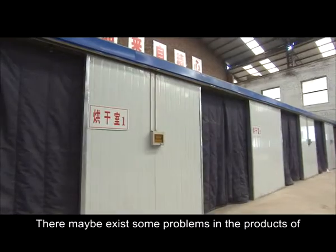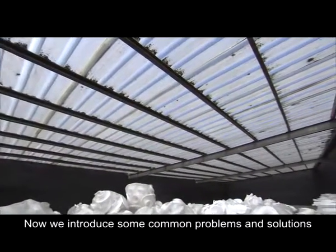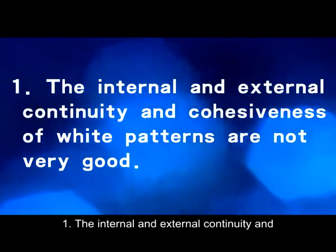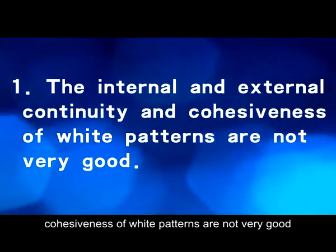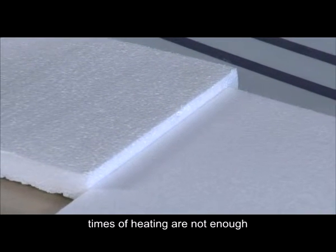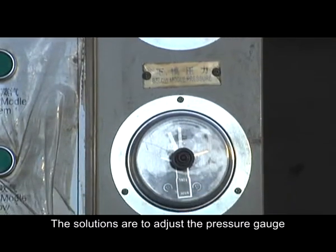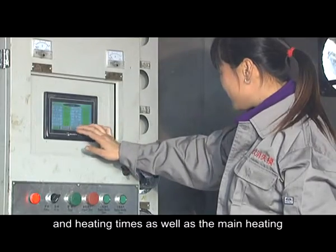There may exist some problems in the products of white patterns. Now we introduce some common problems and solutions. 1. The internal and external continuity and cohesiveness of white patterns are not very good. The reason is that the pressure and times of heating are not enough. The solutions are to adjust the pressure gauge and heating times as well as the main heating.